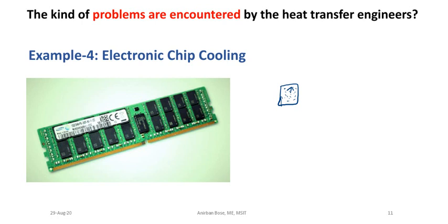If the temperature is well below 50 degrees centigrade, then maybe you will get a very long chip life. But if the temperature on an average is say 65-70 degrees centigrade, it will not last very long. But if the temperature, suppose produced within the chip is say 130 degree, 140 degree, then definitely that chip will directly damage. Okay, so it is very important to remove the heat from the chip. It is required to remove the heat from the chip.